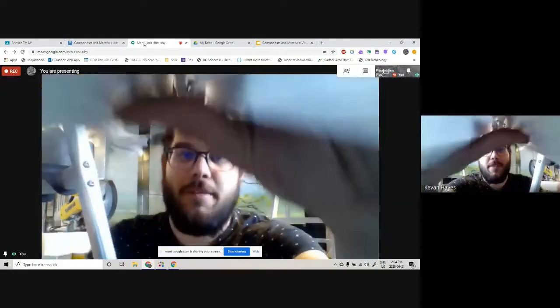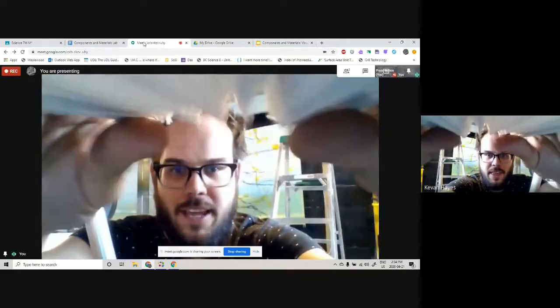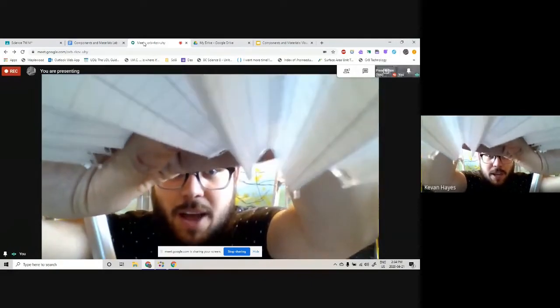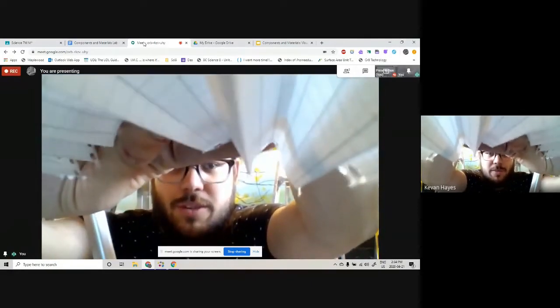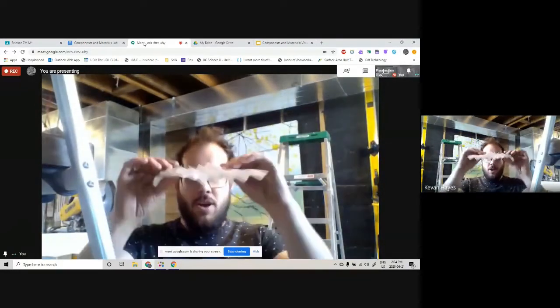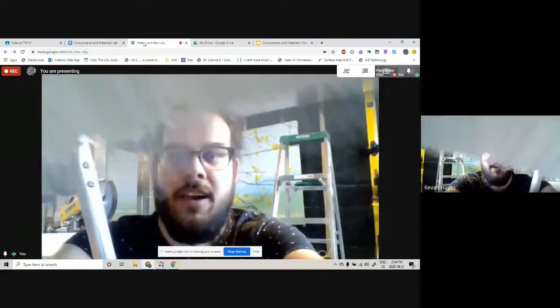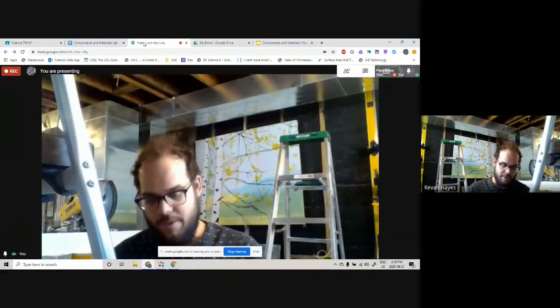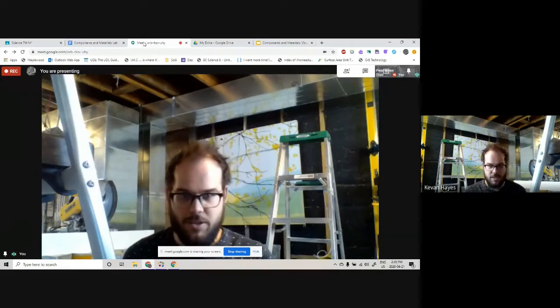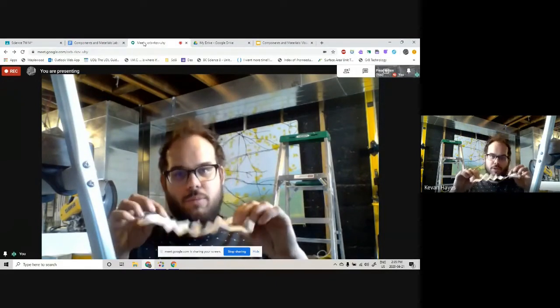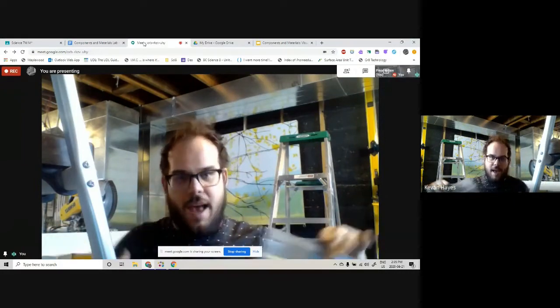We'll just try something. If I put this here like that, right? So this could be like a roof of a shed or something. And as I apply a force on top here, the corrugations help to distribute that load. Whereas if I were to just take a single flat piece of paper without those corrugations, that structure is very weak as a result. So the corrugations are our way of using, again, similar principles to what makes beams and trusses work. But they're a way to create a flat layer of material that's still pretty sturdy, even though it has to span a fairly big gap.